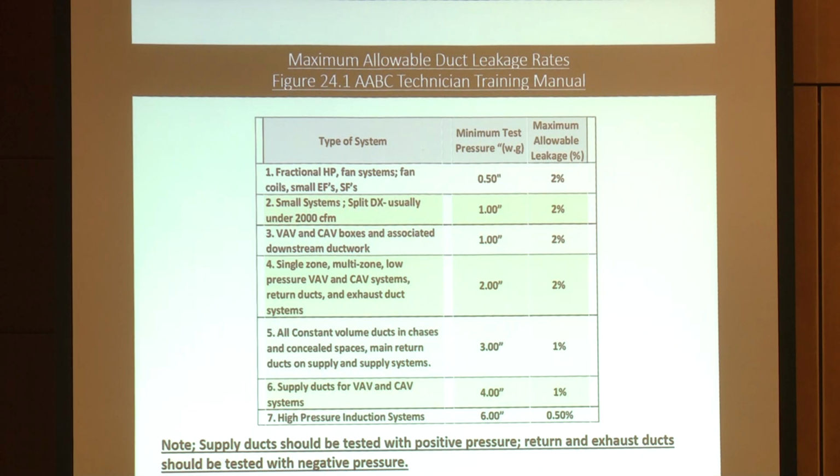It takes a lot of work by the mechanical contractor to seal the duct. And many times, if you have external wrap insulation, by the time we get there, if they've already wrapped the duct, then we don't know it's sealed. So when we test it, we'll find out. We'll find out, because if they didn't seal it, if you don't seal duct, it'll leak 40% easy. Very easy.